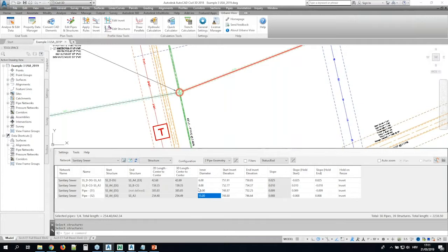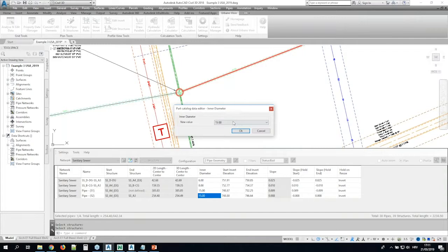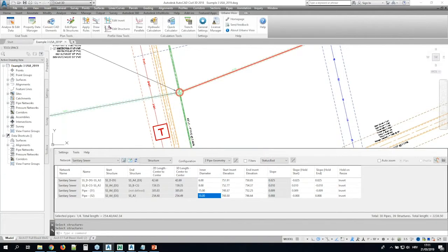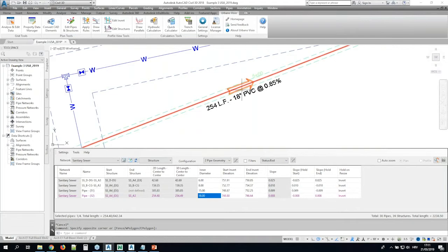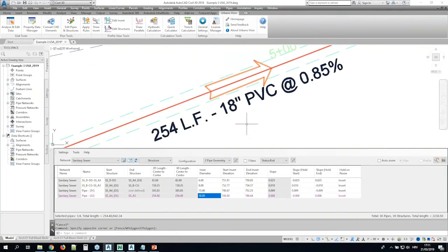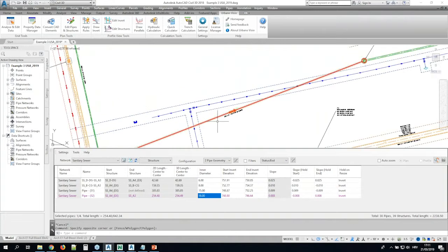at. And to start with the possibilities of editing, so if I want to edit something, I just right-click and I go Edit Value, and for the pipes, it will open up my part list, and I can just simply select a different part from the part list, and it changes immediately. And because this is Civil 3D, it refreshes everything automatically, of course.